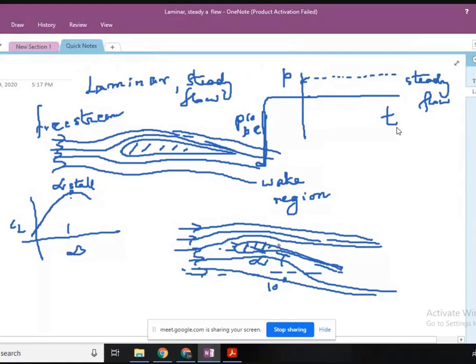The flow has separated because, I'll explain. So now the flow, there is a recirculation region because there is some fluid which cannot go anywhere, but it has to rotate in this region. This is known as recirculation zone. Okay, this is the separation point, flow separation point.